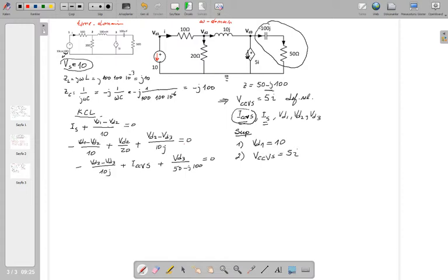Now be careful here. If you write this definition relation, it is not the supplementary equation. Why is that? Because the variables here are not the ones that I am expecting. We are writing the node voltages, so you've got to transfer these variables to node voltages. This one and this one should be transferred to node voltages. When you do it, then it is a supplementary equation.